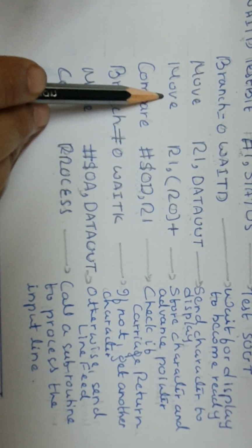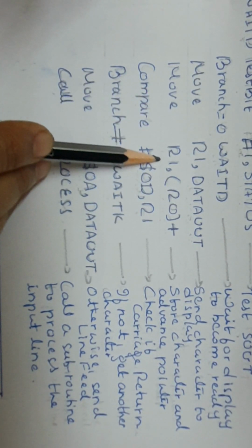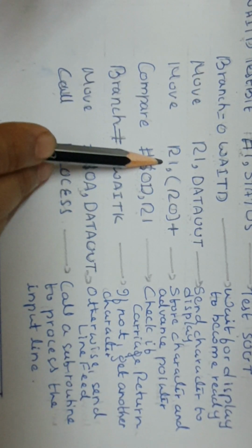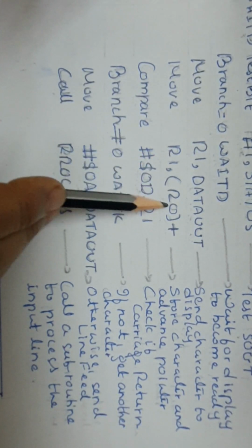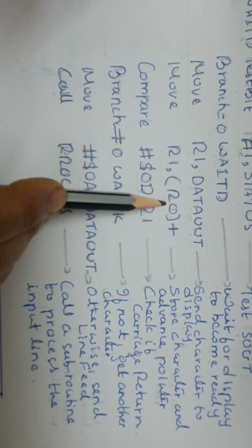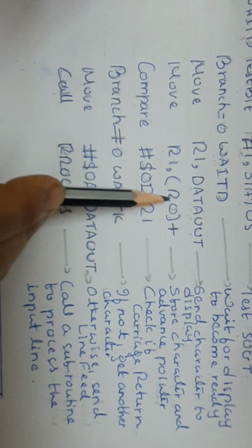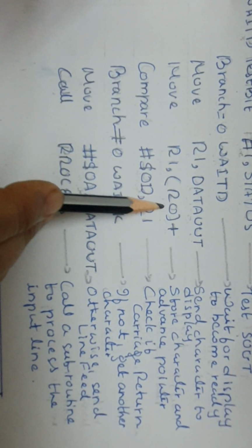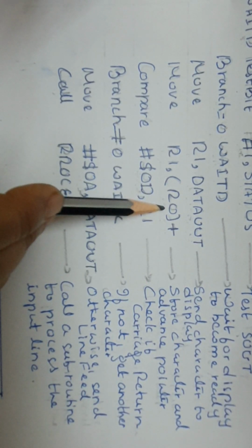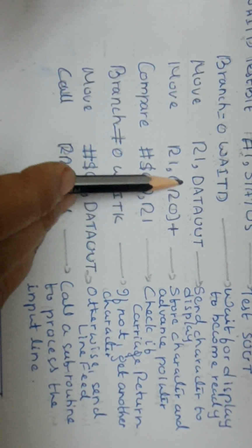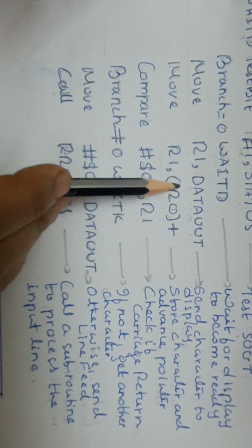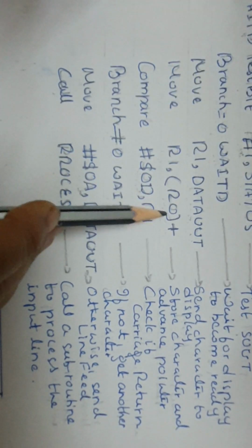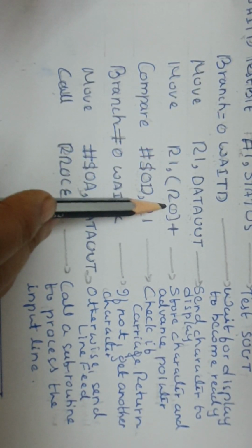So this move instruction will copy the content of R1, the keyboard character which was pressed, to, as the bracket indicates, the address of a memory location. R0 was made a pointer to the buffer or memory, storing the first location address of the buffer where the line of characters is going to be stored. So in that R0 pointed first memory location, the keyboard pressed character is stored.